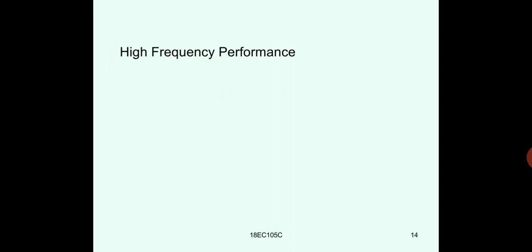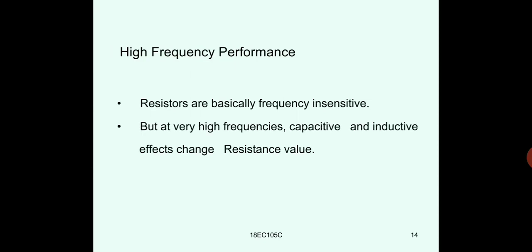Now next one is the high frequency performance of the resistor. Resistors are basically frequency insensitive, but at very high frequencies the capacitive and the inductive effects change the value of the resistance. So in wire-wound resistors there will be some inductive effect due to frequency, and depending on the length of the component there will be capacitive effect at high frequencies.